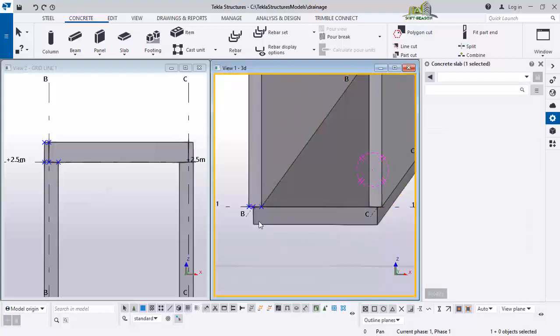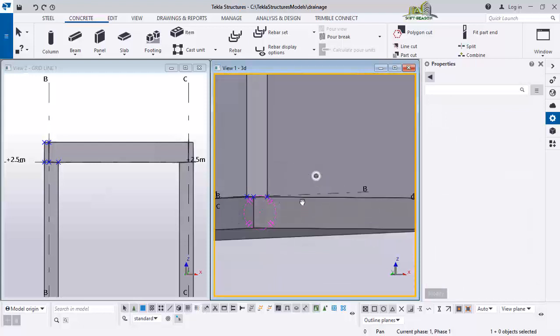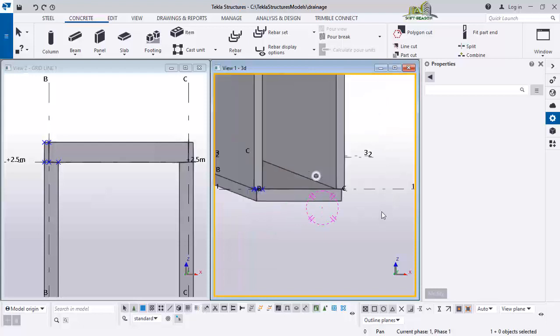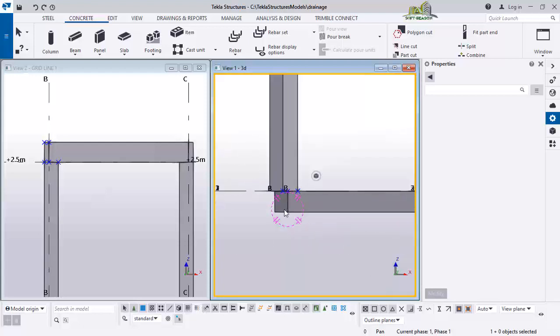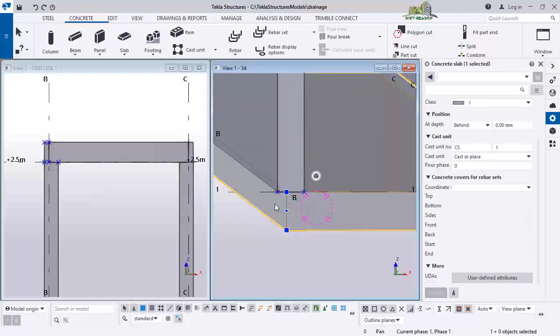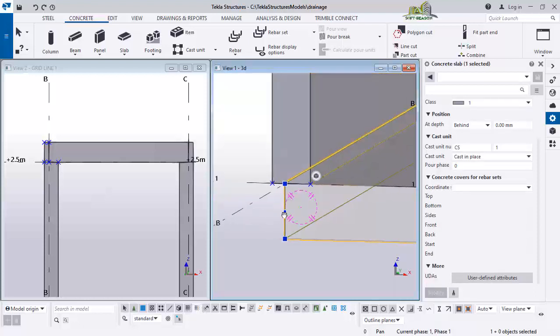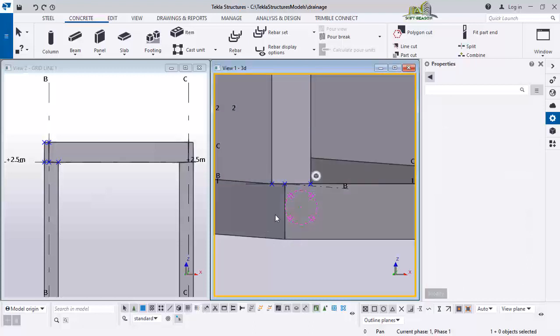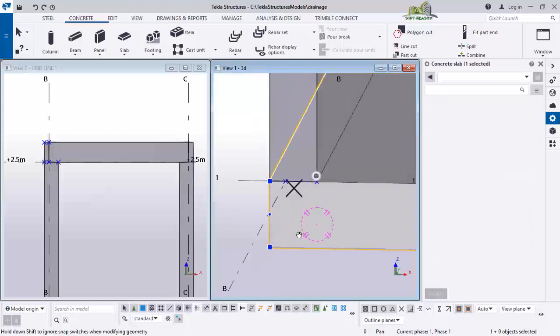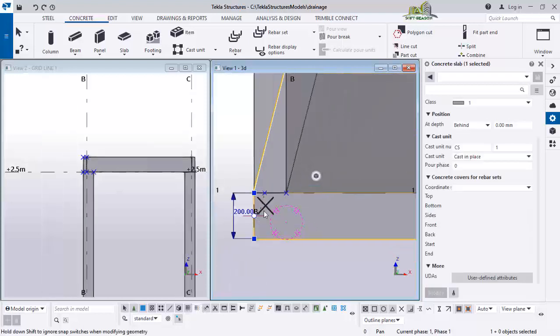Alright, after which you notice that it is not that model. Okay, there is still some part of the wall not directly on the floor. Okay, so what you need to do, you just have to select this, activate your modification, hold down the shift key, click hold and move this. Okay, so turn it like this, select it again, hold down the shift key and pull it out, so it will be in line with the wall of the drain, just like this.